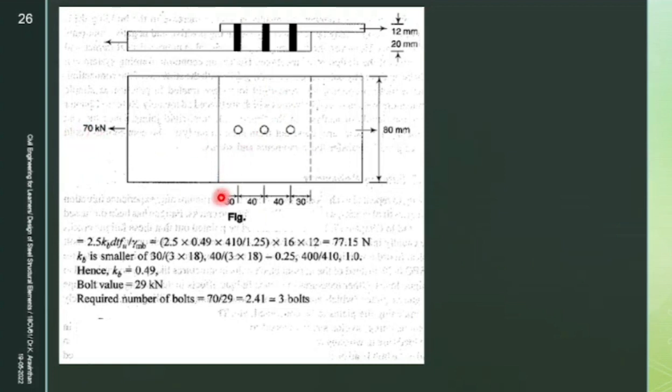Okay. What edge distance is, see, you have a plate here, this is the edge of the plate. From the edge of the plate you cannot bolt exactly at the edge. Have you seen in any steel structure, exactly at the edge of the structure, have they provided any bolt? No. If they are providing, it will break immediately. You should have some distance at the edge. So this is known as edge distance.